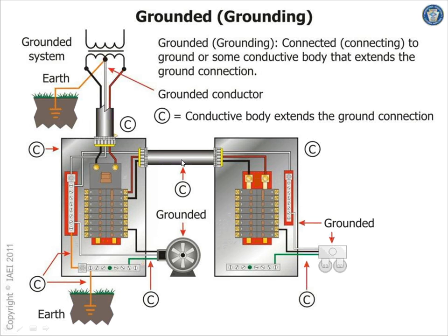Instead of an equipment grounding conductor, you can also use any metallic conduit system approved by the NEC code book, such as EMT, rigid, intermediate, and a bunch of other ones approved as the so-called equipment grounding conductor. So we ground the frame here, we ground the frame of this box, and we also ground the frame of this sub-panel to the main panel. That's called grounding the equipment. Have I established the difference between grounding the system and grounding the equipment? All equipment must be grounded. The system is up to you, though 90% of the systems we use for 600 volts or less are grounded systems.